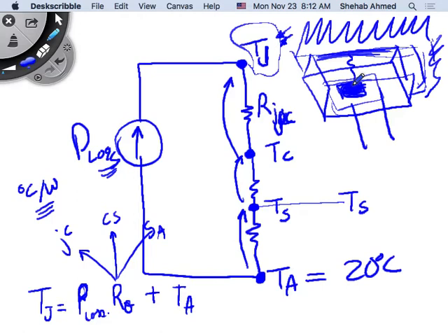what the case looks like, if it's a metal case, you definitely have to always electrically isolate it. If it's a plastic case but with a pad, you have to electrically isolate. If it's a pure plastic case, you don't need to electrically isolate, right? So then we can play with.